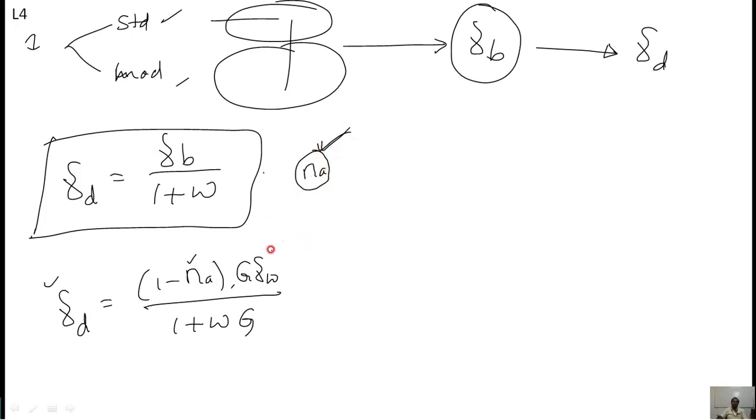Okay. Then sir, I don't know the specific gravity. Don't worry, take the soil and go to the lab, use a pycnometer or density bottle, and by using the pycnometer you can get the specific gravity. Yes sir, you are right. Then sir, I don't know gamma w. That is always constant, 9.81 if you want in kilonewton per meter cube, or 1 gram per centimeter cube. Therefore gamma w is always known to you. Nothing to worry about gamma w.